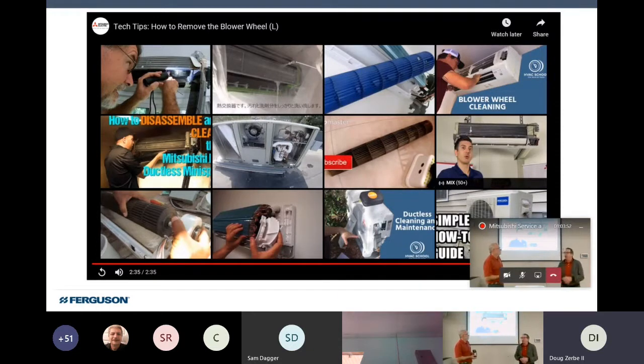Sure. So there are little tips that guys will pick up over time of doing this, but it is really quite simple. The big key is lifting that coil up a little bit, then when you slide it back in, drop the coil back down, re-secure the bearing on the one end of the wheel, and way to go. Yeah, it's good to go.